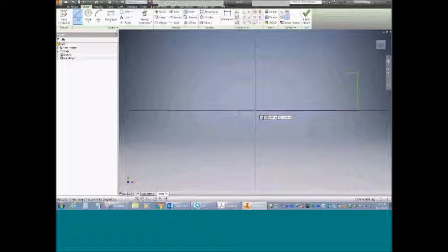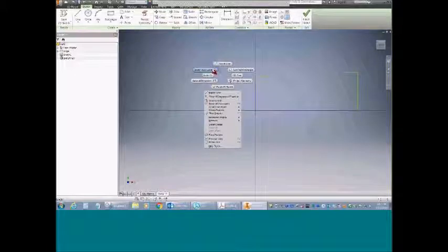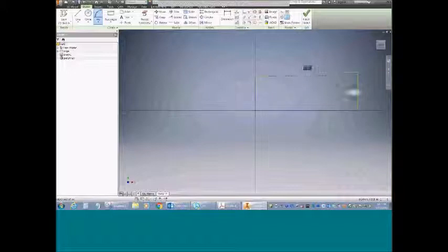Grab that line command again, and get the geometry up there, and then I want an arc for this actually, on my command wheel. So I'm going to put an arc in here. I'll start getting that. Now we have the opportunity to really start talking about constraints and getting students to use as few dimensions as possible and as many constraints as possible, because this is what's going to make the complicated parts easier. So for this one, first thing I would do is probably the collinear constraint, and I would get this line up here in line with that one.